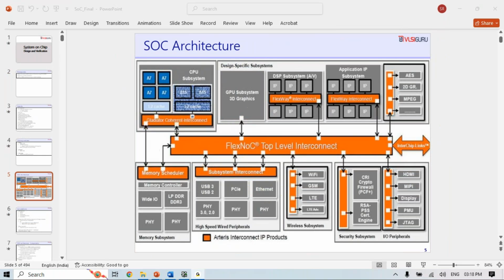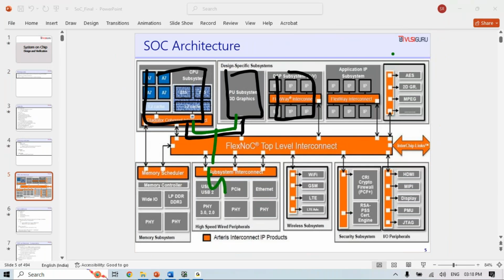Now, also, since you are implementing as two separate chiplets, some lanes may get damaged. To make provision for that, UCIe has allotted some spare lanes. Let's say they may have allotted 4 spare lanes, which can be used for repair purposes. For example, this black lane is not working fine. So you can reconnect, readjust, remap the things and use those spare lanes to correct the faulty lane connection. So this kind of convenience is what UCIe is providing.